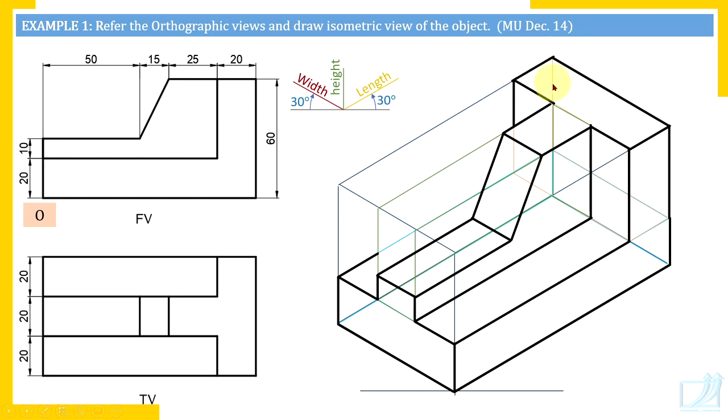But this edge is on the back side. Not only that, this edge is on the right side, and both sides are hidden, that is why this edge is hidden. Now check here. Now since we have removed this portion of the vertical plate, some more portion of this edge is visible, so extend that edge. But it should not overlap on the visible edge. The portion which overlaps on the visible surface, we have not made it dark because that is hidden.